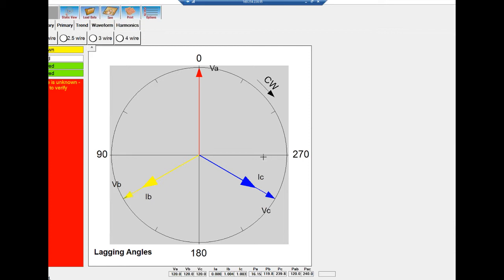So now that I've got the clamp plugged in, if I go over to my primary and hook this up here, we should start seeing 20 amps down at the bottom under IA. Now I got my probe on there, and we now see the 20 amps on my primary under IA. With this tactic, you could use 3 different probes to then measure all 3 primary currents at a site at once and get a power quality reading of all of the primary values instead of just the secondary values. So that is an option. If you have multiple probes, you can plug it in or move the probe around as necessary.